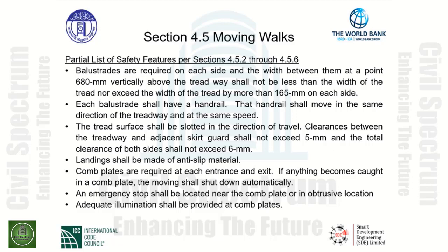The tread surface shall be slotted in the direction of travel. Clearances between the treadway and the adjacent skirt guard shall not exceed 5 millimeters, and the total clearance on both sides shall not exceed 6 millimeters. Landings shall be made of anti-slip material.